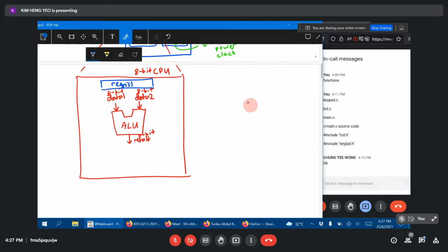registers. So you have registers. The data that the ALU operates on comes from registers, right? And when the ALU produces a result, the result will be stored back into registers. So these registers are temporary storage locations of information inside the CPU. They are the highest speed, very fast, but they are big. So you can't put a lot inside the CPU. That's why you have to have additional memory outside the CPU that you implement as SRAM, data memory.